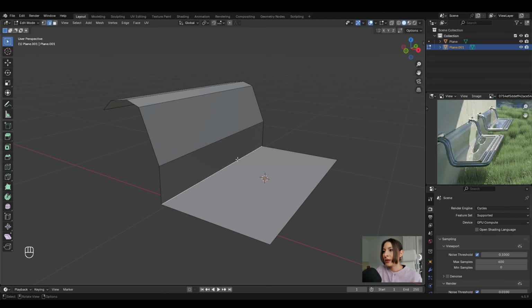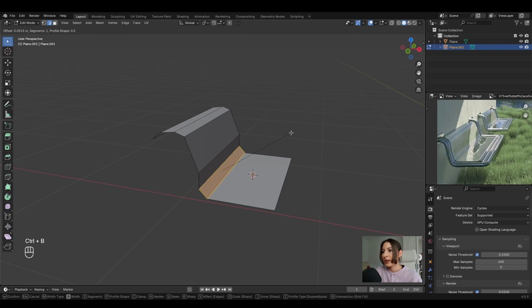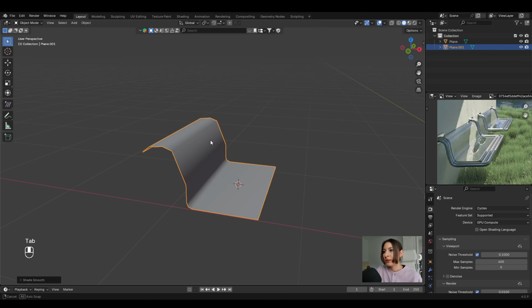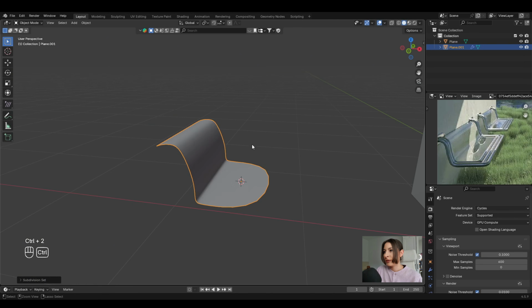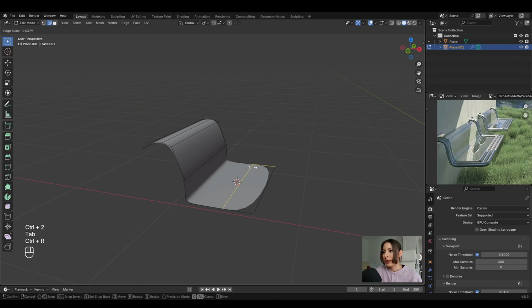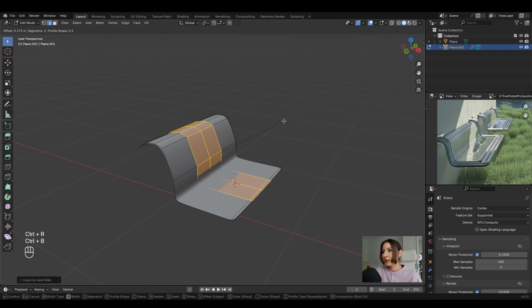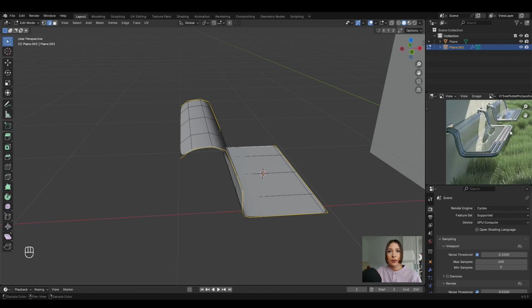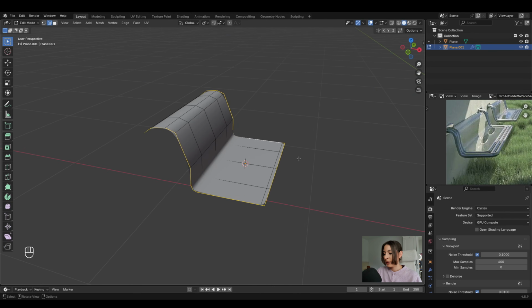And next we can bevel this whole thing. So we can bevel this edge, for example, to make it a bit rounder. Something like this. And right click, shade smooth. Next we can give it a subdivision. And we have to add some more edges. And maybe one here. Let's select this whole edge by holding Alt and Shift and clicking these. And they have these round kind of shapes. We can select them and Shift D and P selection.